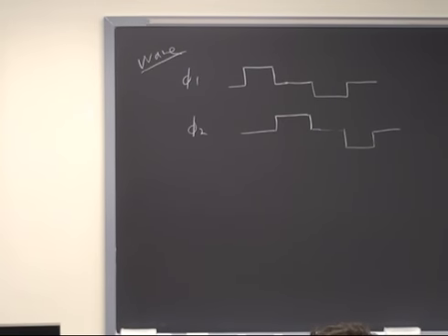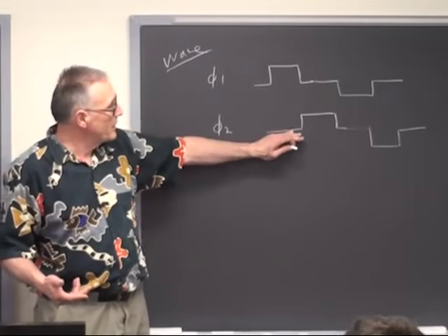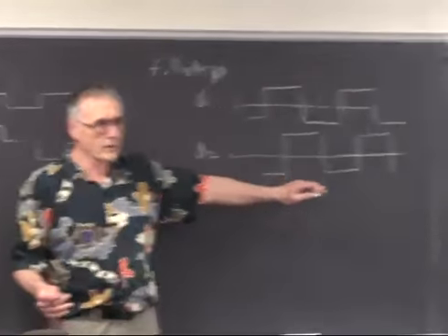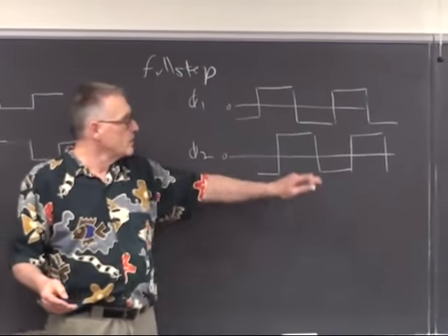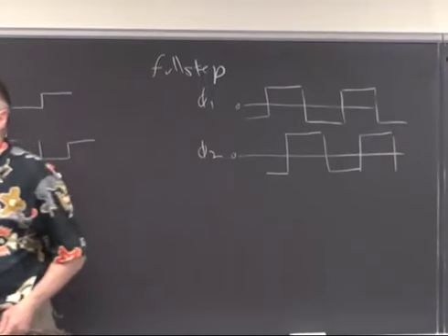So let's say you overspec your motor and you don't need all the torque it can produce, then you might go to some scheme like this. Whereas if you underspecified the motor and you need all the torque it can produce, you might go to a full step option. Also, there's another condition.